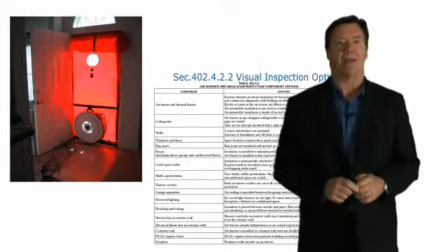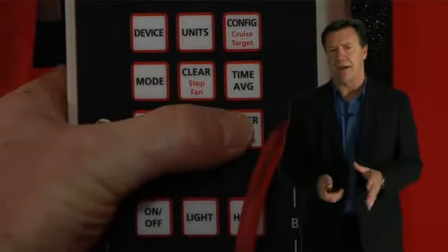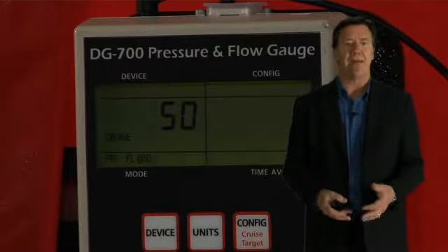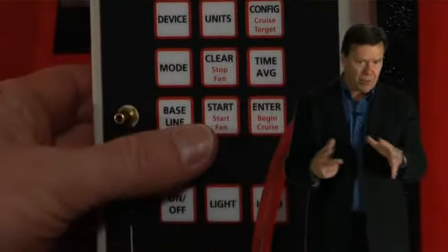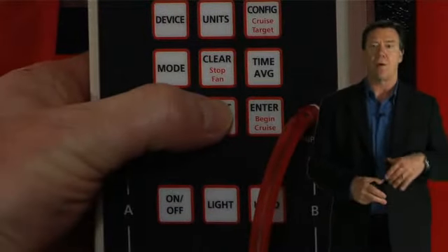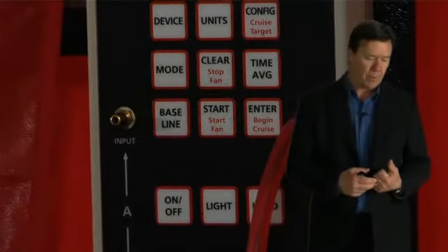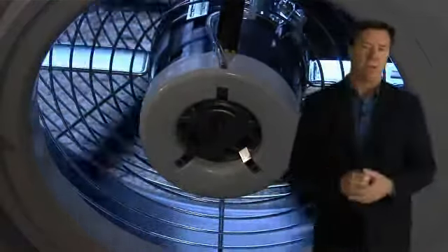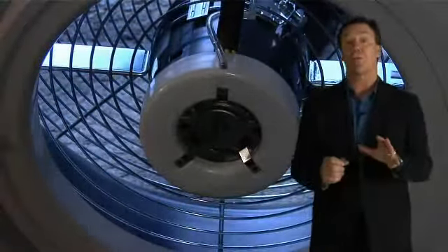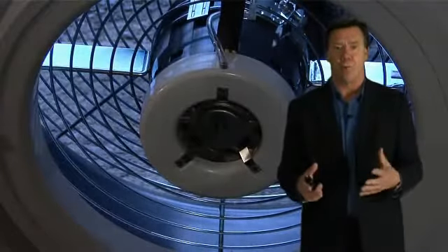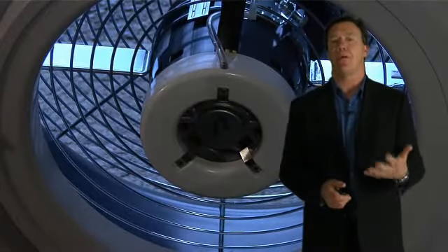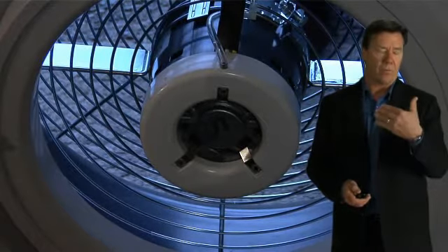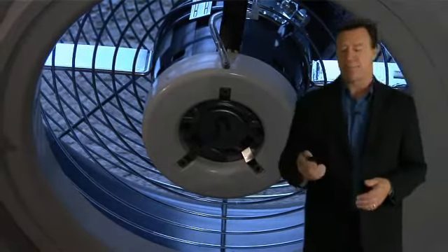Now, what we're looking at here is the blower door, which is basically a fan that fits in a doorway. You turn on this fan, and the fan has some manometers that measure pressure differences. Through an algorithm and a computer program, we can take measurements of the airflow through that house, do some simple calculations, and determine what the air exchange rate of the home is, or how many cubic feet of air per minute is flowing out of the house. And there are certain requirements that we have to follow to meet that.